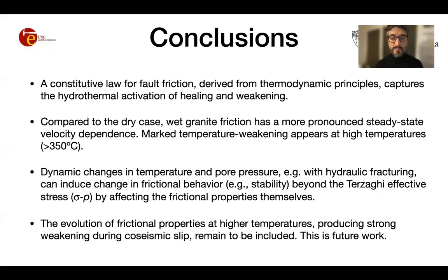Dynamic changes in temperature and pore pressure, for example, during hydraulic fracturing, can induce changes in frictional behavior, for example fault stability, that go way beyond the Terzaghi effective stress, sigma minus p, by directly affecting the frictional properties themselves. The evolution of frictional properties at higher temperatures, producing strong weakening during post-seismic slip, remains to be included in this model, and this is a direction for future work.